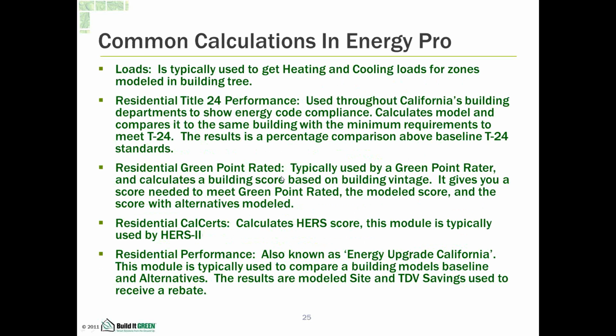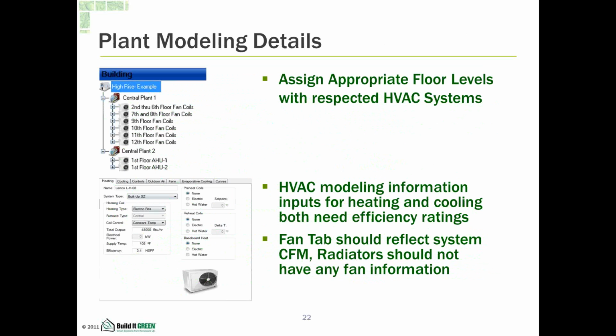Okay, so going back to the slides here. So when modeling your HVAC systems, again, model your HVAC systems with the zones that are attributed with it. So in this example, we have different systems serving different floor levels. So you want to make sure that you call that out consistently and clearly, and if you decide to combine all systems, make sure they're a similar fuel type and you average their efficiencies. But if they're different fuel types, you definitely want to split out your systems.